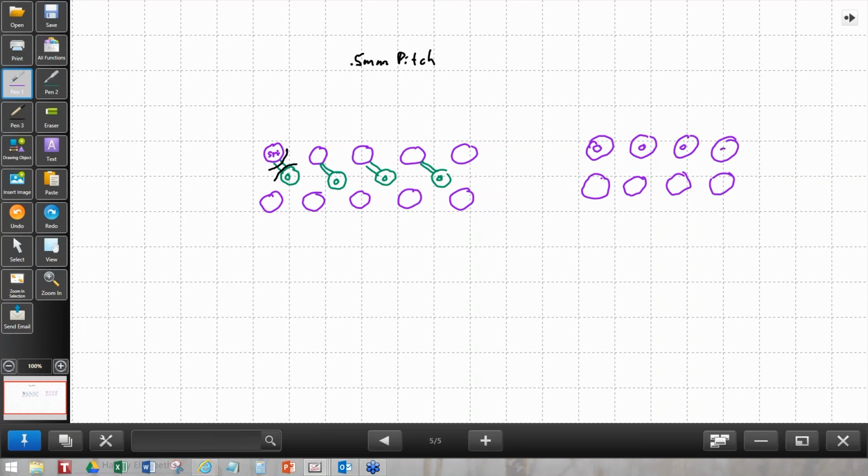So you have a surface mount pad, you have a via. The problem with this is that if I have a pad, and then I have the via actually inside the pad with its hole, you're going to end up with a hole drilled all the way through the pad. Well, that's going to suck the solder away, so you have no way to deal with it with solder mask because you can't put solder mask over the pad. Hence, it's necessary to plug the via. Plugging of vias is done a lot on these very small things. It is an expensive process.